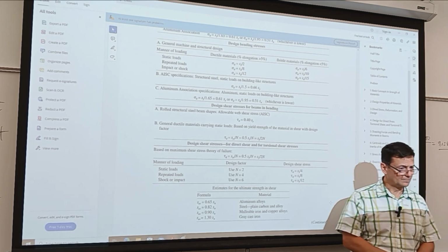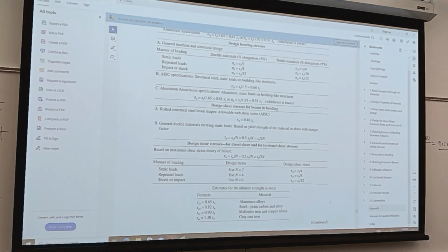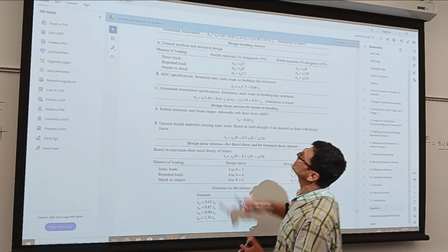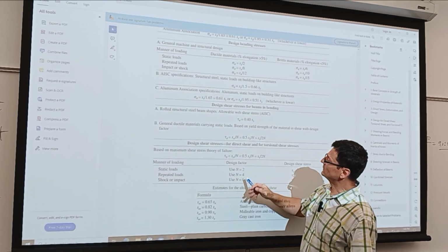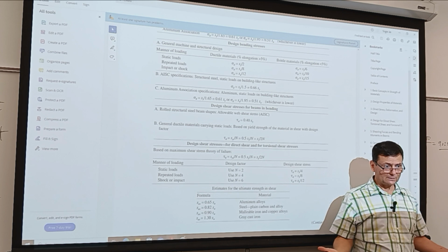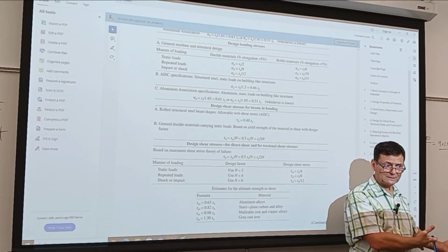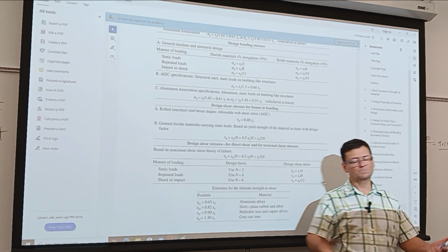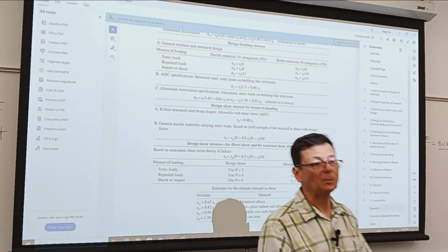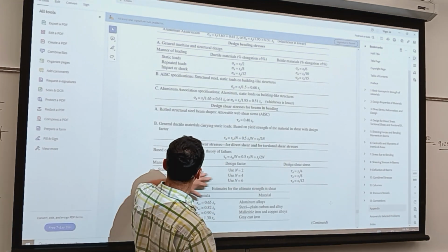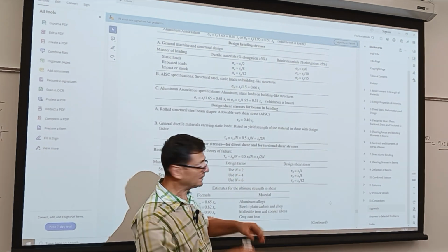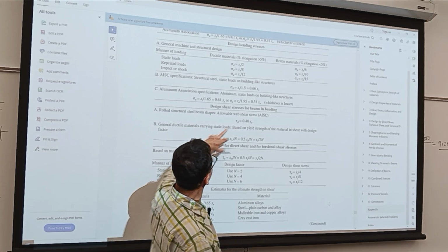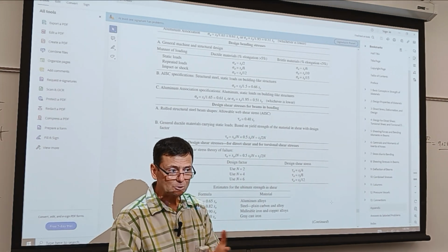Okay? Question: for the design factor, is that pretty much the industry standard across the board for civil engineering, or is that calculated? Yeah, there's code. I mean, here, American Institute of Steel Construction, and it depends on the industry. Aerospace industry, because they want to design lightweight. Again, what we're going to discuss is why have a design factor. So why don't we go to the limit? Like 2, you can double the load and only start to yield the material. So why do you do this?